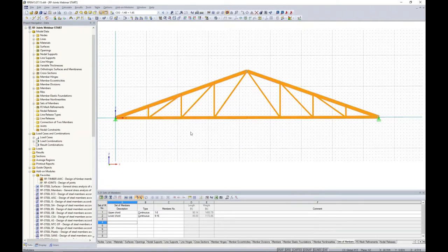then we'll get the generation of our timber structure here. Then I did add a pin support on my left-hand side and a simple roller support on my right-hand side. Now, the other thing that we need to take care of is that when I did generate the truss, a fully rigid connection was available at the top of the truss, also on the left and the right.